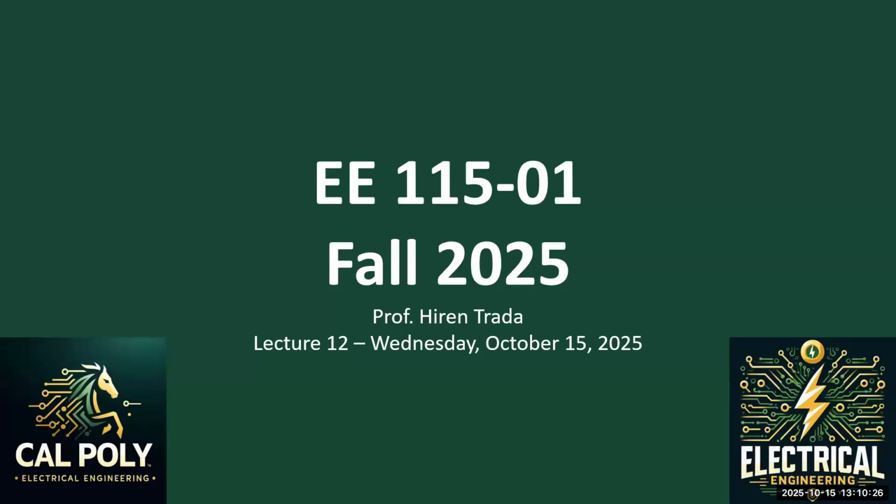Good afternoon. Let's continue with our discussion about source resistances. In the last few lectures, we've talked about sources, voltage sources, current sources, and how a real life source will have some resistance, and that source resistance will absorb some of the energy. So any design of a power source needs to take into account the internal source resistance.